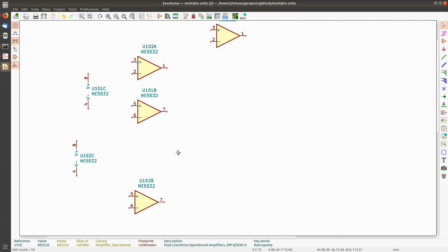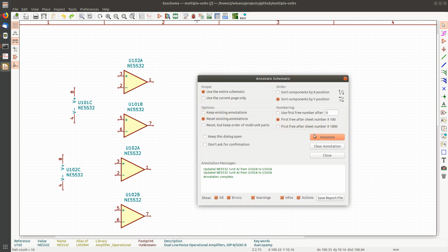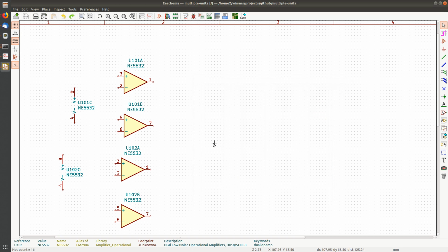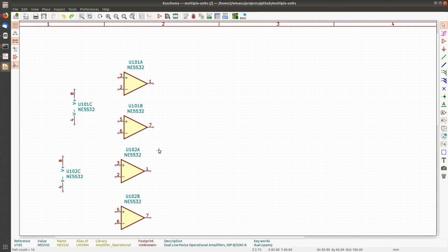Now, if you do this, this is okay, but if you've already routed your board, what you've now done is you've moved traces from one physical device completely to another one. That can be incredibly confusing. So let's undo this and re-annotate it back the way it was, and show you what you want to do if you end up doing this in your schematic and you decide to re-annotate your schematic. Well, if this does sort of happen,